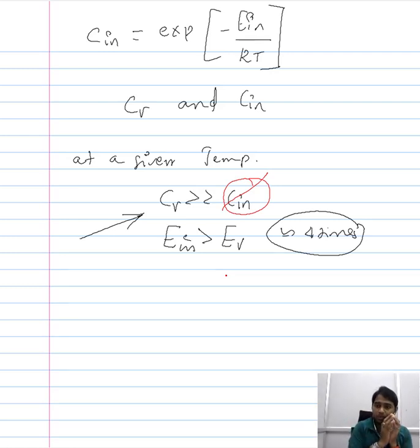The stable point defect at a given temperature is largely due to vacancies rather than interstitial atoms. Even the interstitial atoms, we don't observe in equal amounts at a given temperature. The point defects are largely confined to vacancies at a given temperature.